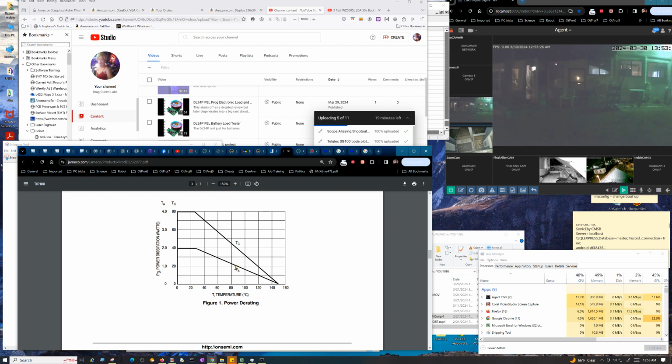So in other words, if you had a 90-degree reading inside your enclosure right next to the component and more or less underneath it, you're trying to measure the incoming air, basically that incoming air temperature can't be any higher than 90 degrees.